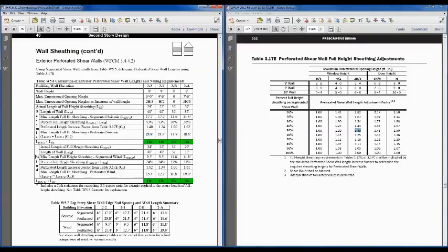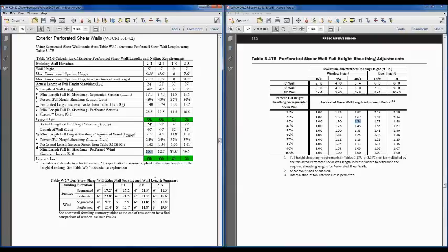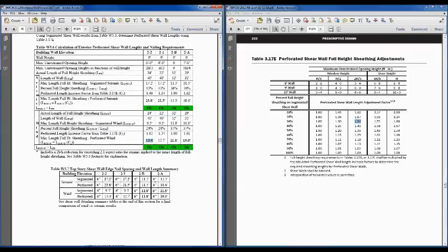The wind load analysis is going to be very comparable. In the earlier segmented approach, that required 9.5 feet. Over a 40-foot wall, that's about 24%. We come up here to between 20 and 30. We're going to interpolate between 1.67 and 1.54. It gives us a 1.62 factor. Multiply that, a 60% increase over the 9.5 feet, and we end up with 15 feet of wall, and that's plenty to work with the 24 feet that we have.